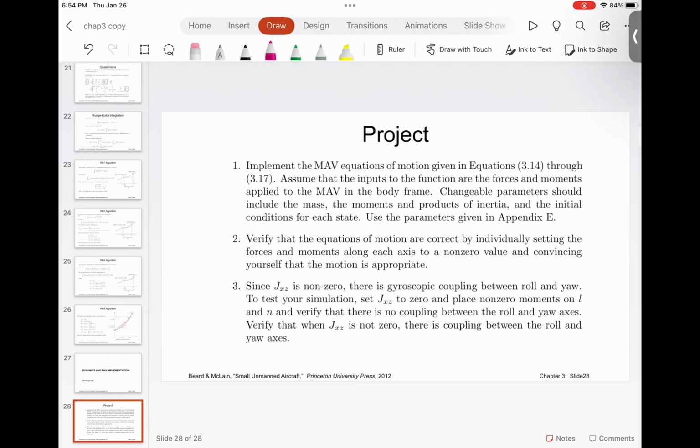There are some crazy planes, but to turn a flying aircraft, it does not require a lot of motion. If you are flying and get a window seat, look at those flaps; you will notice that when the aircraft is turning, the movement of those flaps is very, very small. Even though the motion is small, the cumulative effect on the boundary layer and aerodynamic forces is huge. That makes the aircraft turn.